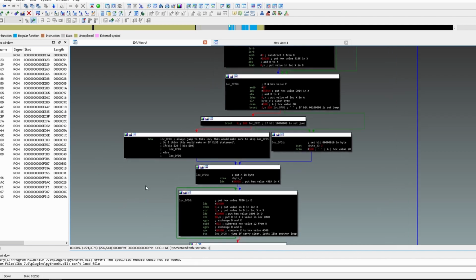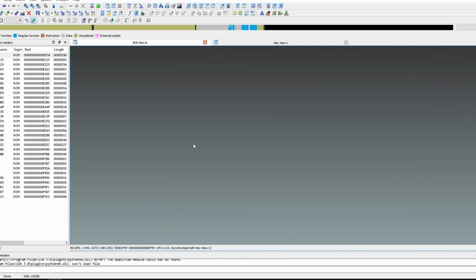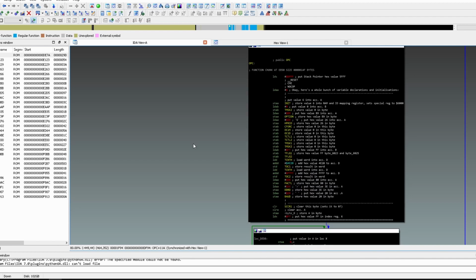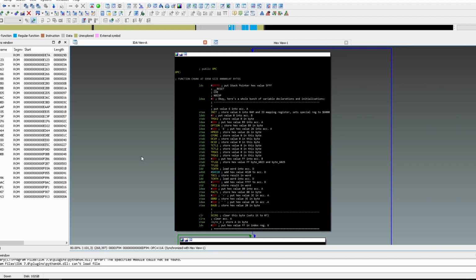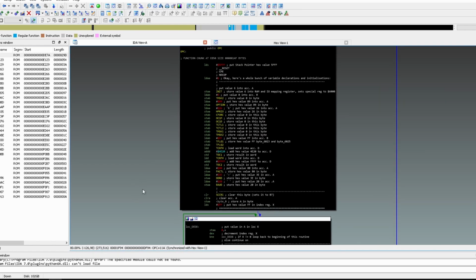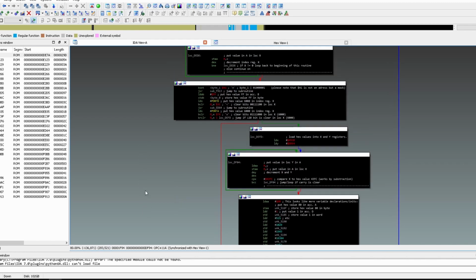And yeah, it's a lot. So this is the reset vector, the entry function. So the main function you'd have in C, and the C code I'll get to in a second. And well, this is basically just all assembly, 6800 assembly.